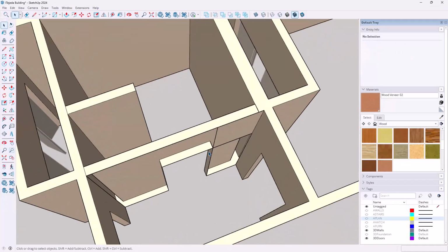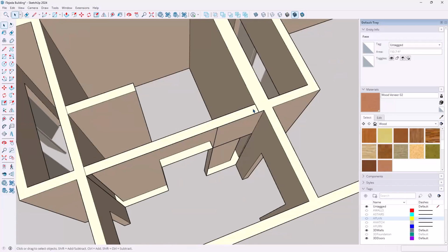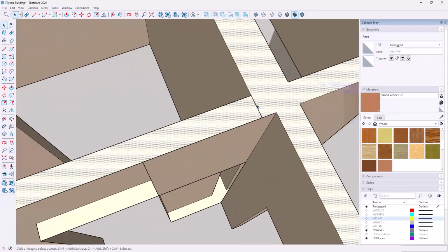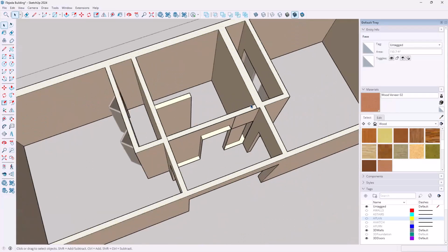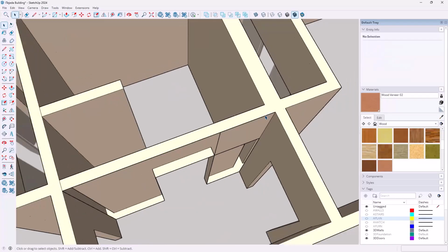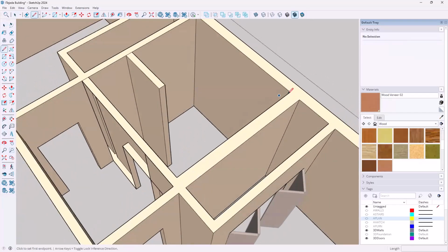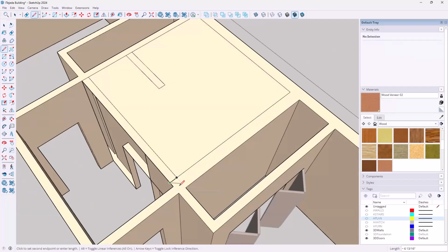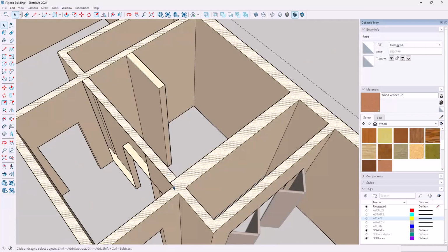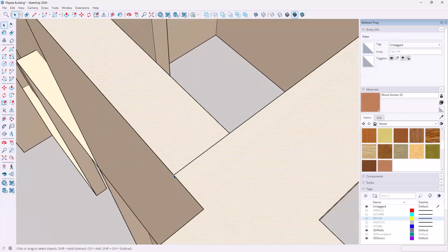And then I'm going to see what happens if I try to push pull this straight down. No, it's push pulling something else. So that line didn't really separate anything. So I'm going to click right there, select the line and delete it. So that had no results. Let's try this again. Line from here and go straight across there. Okay. And then I take that surface and delete. And now this should be separated and it's not. So this is really interesting because that means it's not going all the way to the edge.